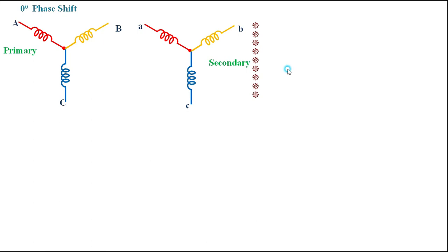the first thing I will draw is for the primary side. That is A. This is the voltage across phase A. This is B, and this is C. Then in the secondary, in the same plane you have to draw A, with whatever ratio you have got. Either you can draw a smaller vector here or a bigger vector depending upon the transformation ratio. This is B and C.